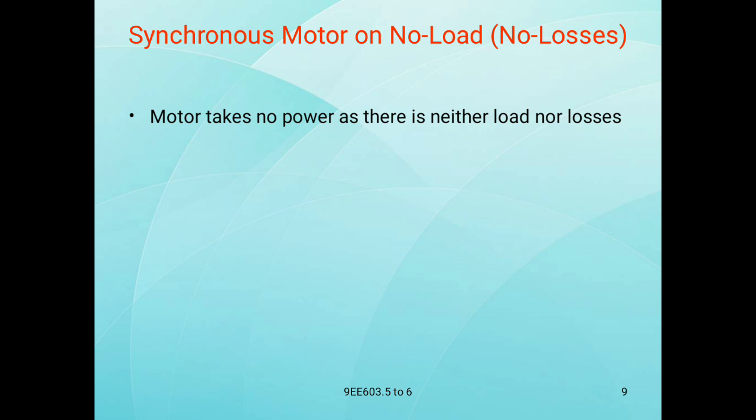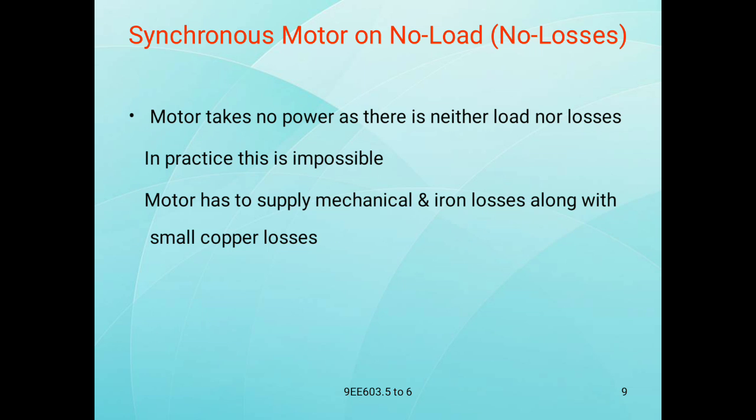Now the motor takes no power as there is neither load nor losses. In actual practice this is impossible. Some armature current is drawn from the supply by the stator, so the motor has to supply the mechanical and iron losses along with small copper losses.